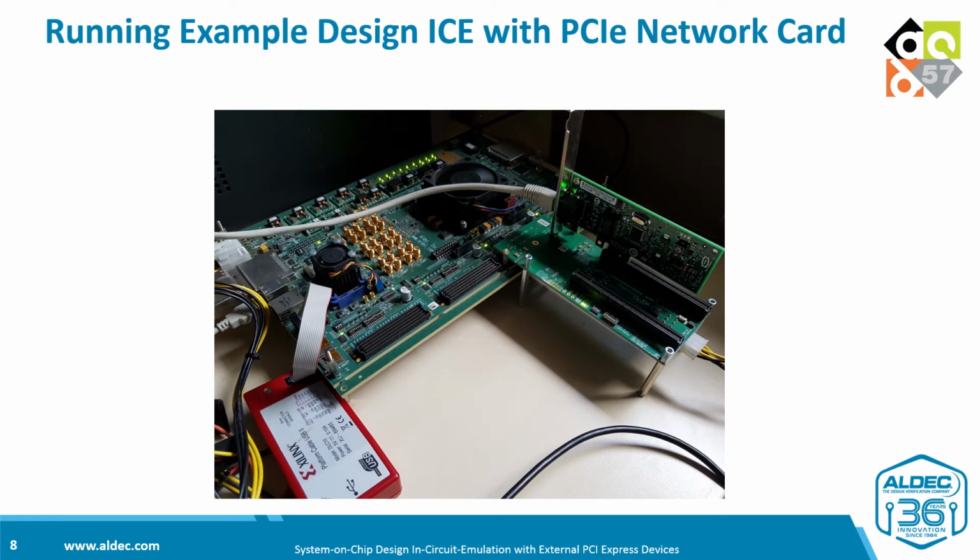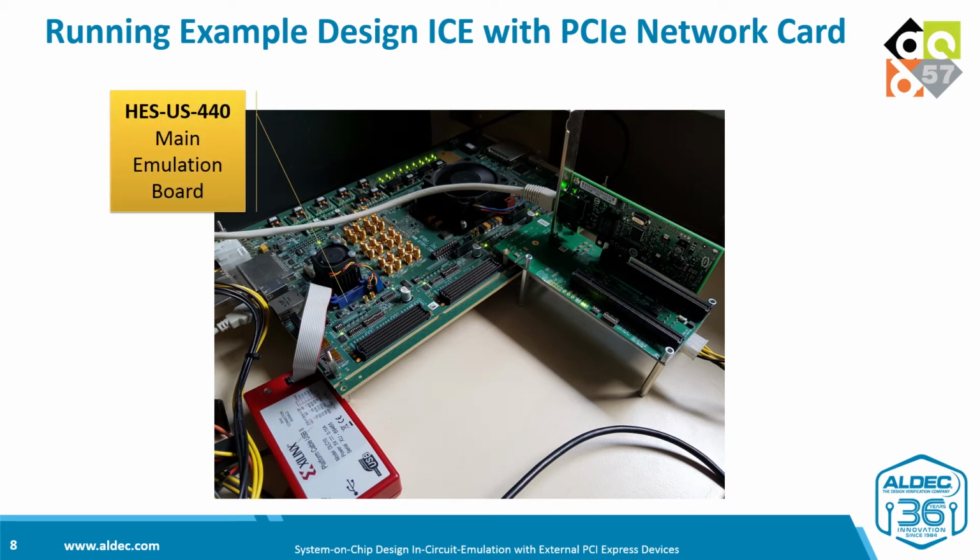After I finished the design, there was the time for running it in hardware. For emulation, I have used the Aldec HES US440 board that features the Xilinx UltraScale US440 FPGA. Next to it is the FMC PCIe extension daughter card, which allows connecting standard off-the-shelf PCI Express cards, and it connects with the HES mainboard using non-proprietary FMC HPC connectors compliant with the VITA 57.1 and 2010 standard.